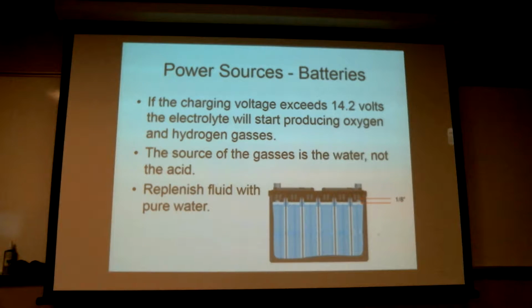So, any gases that come off are not from the acid, it's from the water. And it's due to either direct splitting of the water or evaporation. It's usually a combination of both. That means when you put new fluid back in there, it should only be pure water. Okay, distilled or pure water. Distilled means it's purified. No tap water. We've got stuff in it.